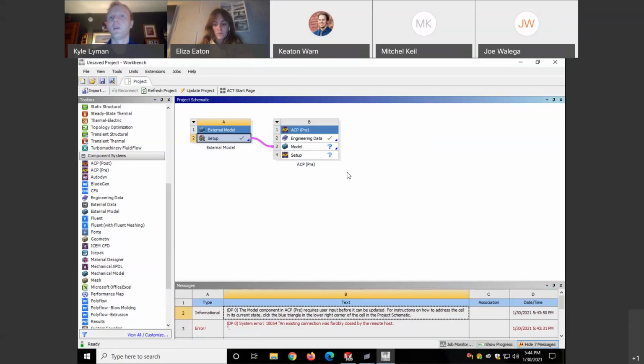And so you don't want that to be in an area of interest if you're really trying to nail down what the stress actually is there. It can be great for making a transition in a low gradient area, right, but you can make it look artificially stiff. Okay, that's good to know.